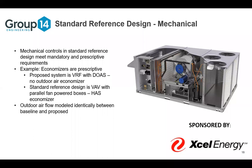That system has an airside economizer. And so you want to make sure that it's listed that they are modeling the airside economizer in the baseline design and not in the proposed design, unless they designed it, which would be expensive. Unless they designed it that way, they're going to take a hit for not providing that airside economizer in the proposed design. Now, if they were complying with the code via ComCheck, they would have to provide that airside economizer because it's a prescriptive requirement in the mechanical section.